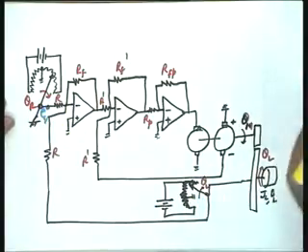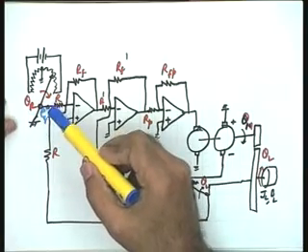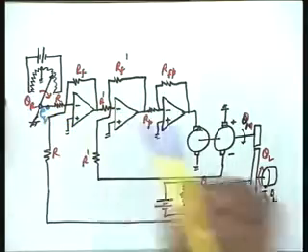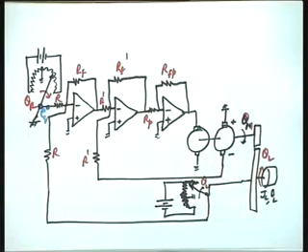So in that case, a potentiometer is also adding to nonlinearity, but in my mathematical model at this point I am neglecting that nonlinearity, and I am assuming a linear relationship between this voltage and this position theta R. At a later stage I will come to other devices which are better than the potentiometer in terms of linear behavior and which are more extensively used in industry.